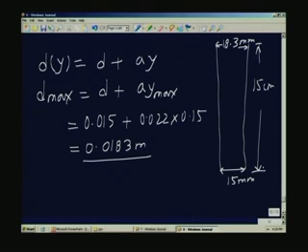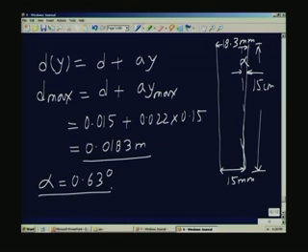So, this is designed for the rotameter. Inner diameter, entry diameter 15 millimeters, exit diameter 18.3 millimeters, the length of the taper tube is 15 centimeters, and the taper parameter is the value which we just described. Actually, you can work it out, the taper parameter will also mean this angle between the vertical, this angle you can give in terms of the angle. That angle turns out to be a very small angle actually, that will be 0.628 degrees. So, that angle, if I call it alpha, alpha is 0.63 degrees, a small angle for the taper.